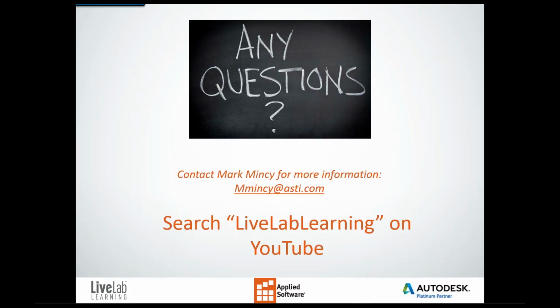So basically, anyone on your team, whoever is the lowest common denominator of their version, that's the version you have to go with. So unfortunately, Kit, if your engineer is working on a previous version, you also be working on that previous version if they cannot upgrade. Now, you can get with the salesperson, if you're on subscription, you can get up to 4 back. So if you're on 2016, you can have 14, 13, I believe, and then you can open up any drawing and work in that version. But there is no saving down. Sorry.